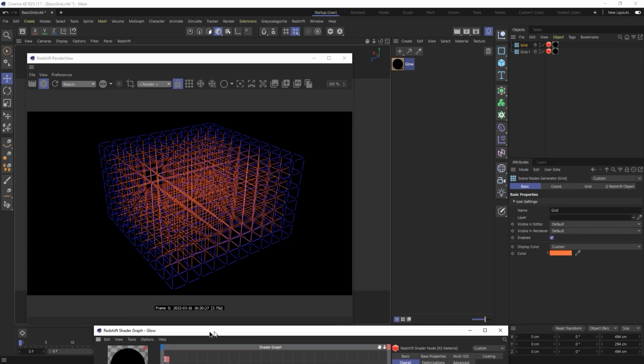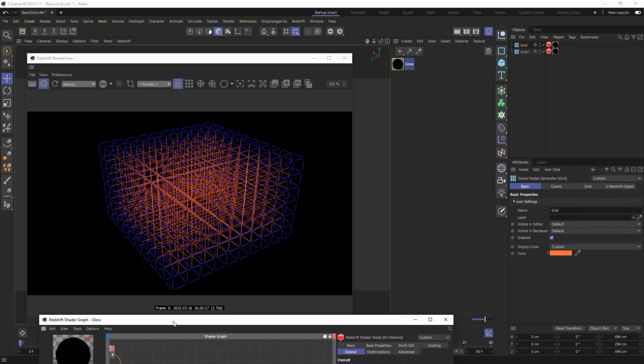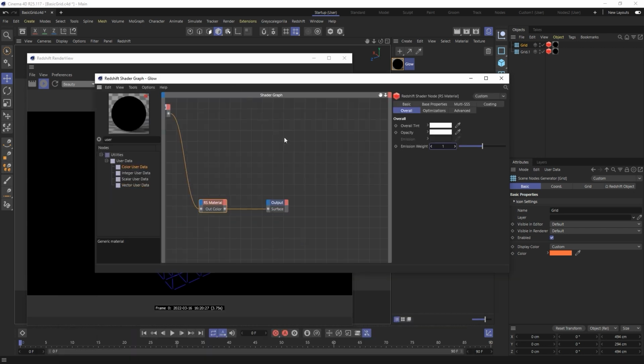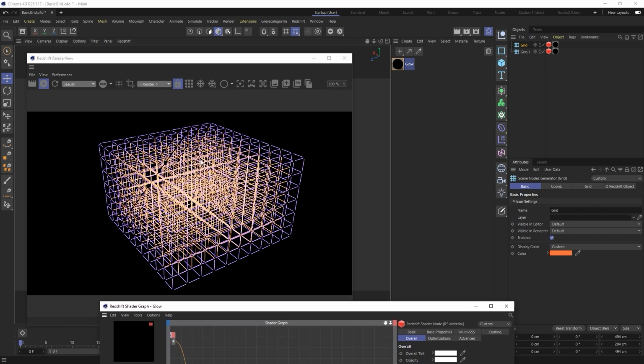But here's something that I like to do. I like to get a little bit of glow going onto these materials. So let's make it overly bright. And sometimes I can go overboard. So let's try going a little bit easy on it. I'm going to say an emission strength of 10. So it's 10 times brighter than normal. Now, immediately you see these start getting oversaturated.